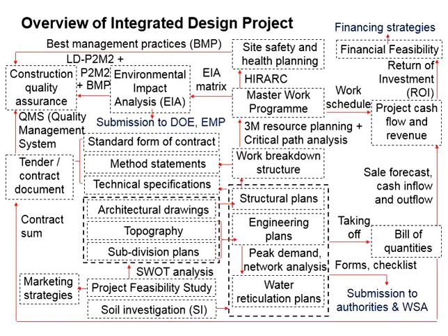Arrange them in proper sequence and forecast the durations required based on the amount of resources put into the project. Then you will work out the master work program. Based on the master work program, you can perform the critical path analysis to evaluate the flexibility of the master work program produced.